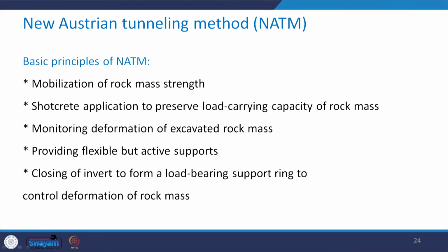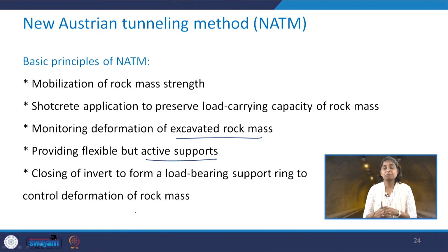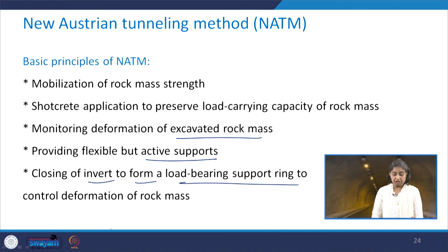Then the monitoring of the deformation of the excavated rock mass. We need to provide flexible but active supports. It should not be so flexible that it is not able to restrain any deformation, so we need to be careful. Then closing of the invert to form a load bearing support ring to control the deformation of the rock mass. You remember, a tube will behave as a tube only when its end is closed.